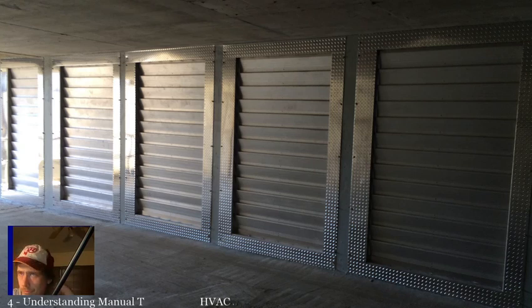Yep. All right, so one thing to remember is on gas equipment, grounds are very important. If you have a bad ground, I don't know if you guys have ever had a vehicle with a bad ground, but a vehicle with a bad ground can start to act really funny, right? The computer doesn't work right. That's for slightly different reasons than a furnace, but it's the same principle. You have to have good grounds on most equipment with circuit boards, but it's even more important on a furnace than something else.